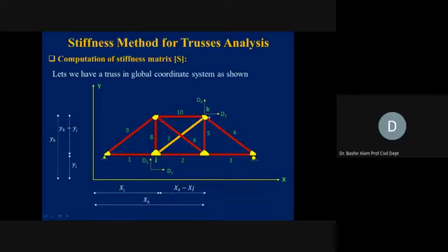Similarly here, at joint K now of this member 7, we have D3 and D4. D3 is the horizontal and D4 is the vertical. So horizontal and vertical, again, these are the global displacements. What will be its local displacements when we start pushing this now, or when we start stretching it along the length of the member now, along the local axis of this member? So that will become our D1.